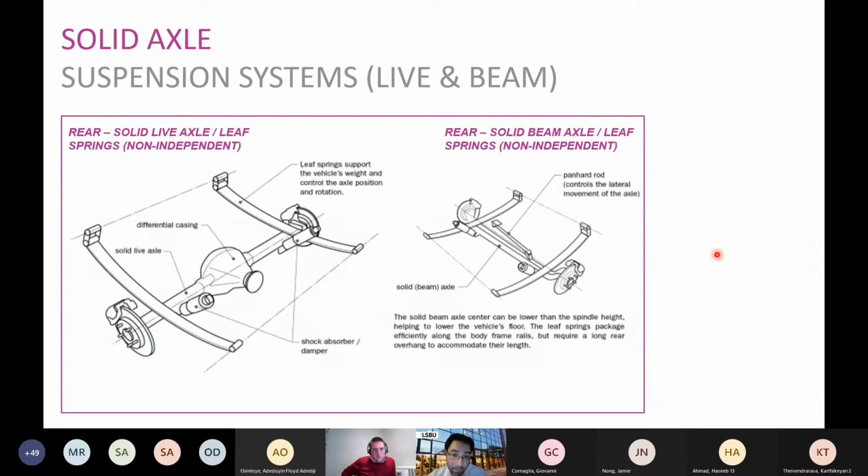Essentially it limits the amount of lateral movement that the suspension system has. Well, it may sound crude, it's a very effective way of limiting that movement. As the vehicle is bouncing up and down, there is this tendency for lateral movement to creep in, and it's a really efficient way of limiting it.